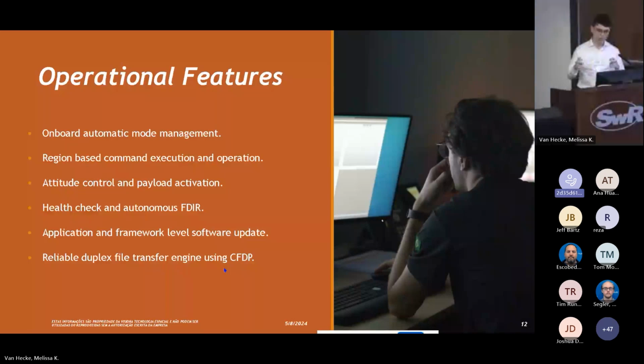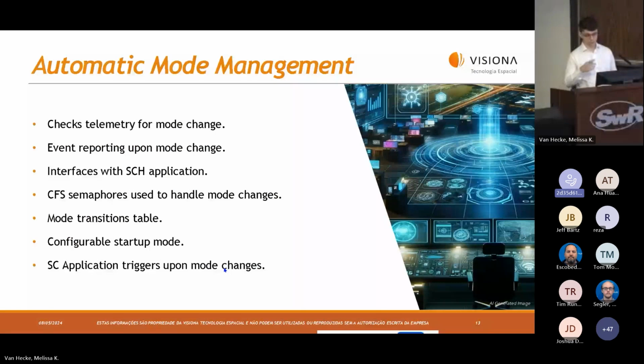Now, taking a more technical deep dive into the aspects denoted, the automatic mode management engine was, as most of you may imagine, a custom application developed by the team at Visiona, and it works basically by checking telemetry packets, and upon meeting certain conditions, it reports events saying that the mode was in fact changed, as well as triggering execution of stored command tables to perform operations upon those mode changes.